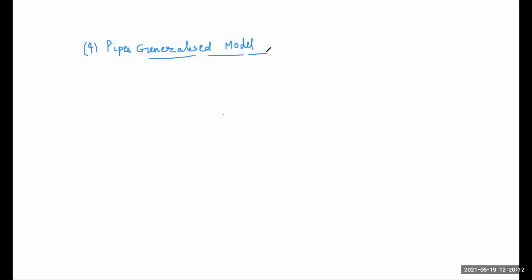One is the Greenshields model, the next one is the Greenberg model, and the next one is Underwood's exponential method. So basically all these models are related to traffic parameters. With the help of these models, we calculate the relationship between K, Q and V. In order to generalize the modeling approach, Pipes introduced a parameter n. So basically in this method we take the help of the parameter n.